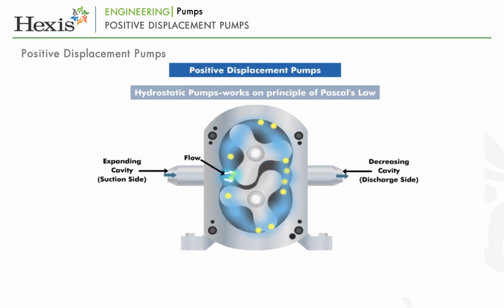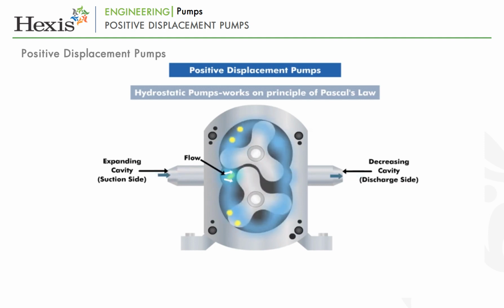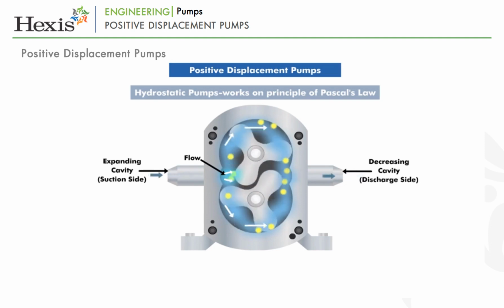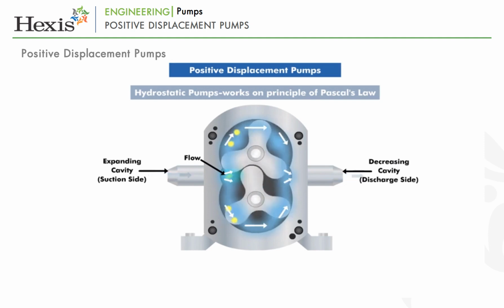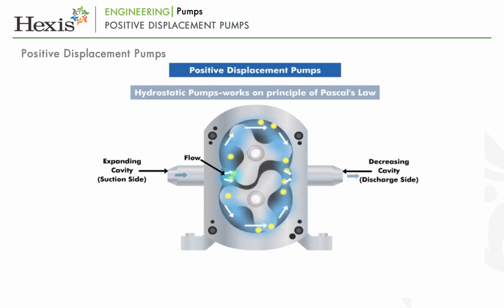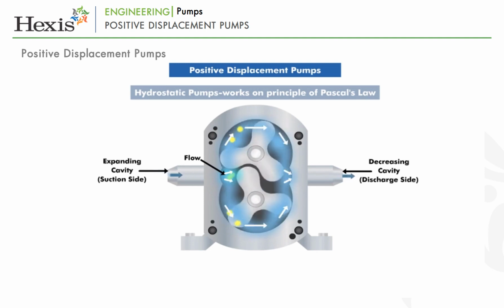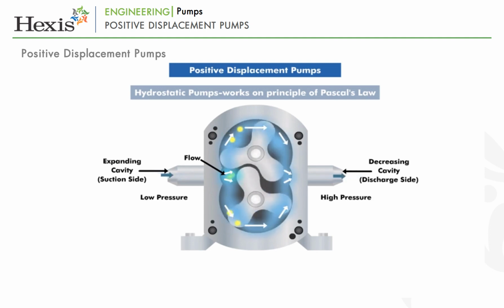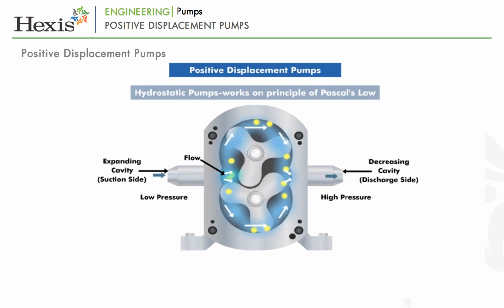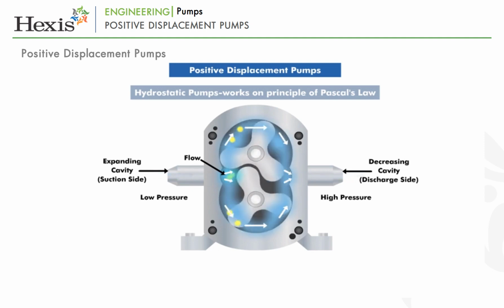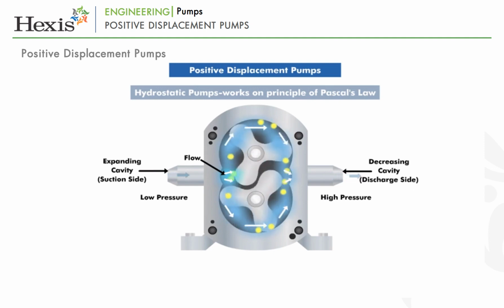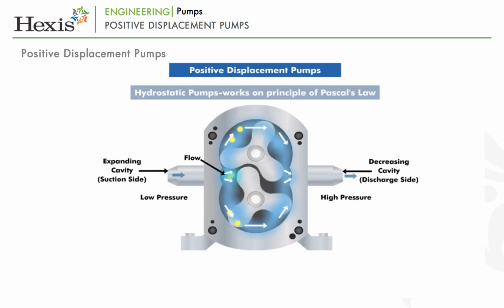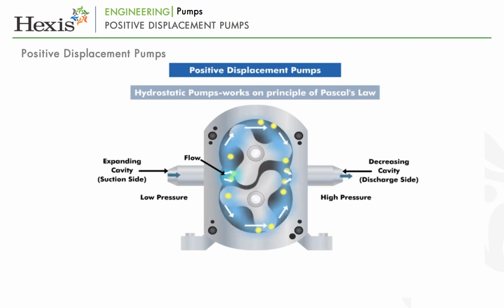The liquid flows into the pumps as the cavity on the suction side expands, and the liquid flows out of the discharge, most typically using a rotary, reciprocating, or diaphragm method to move fluid as the cavity collapses. In other words, it alternates filling a space with liquid within the pump and then moves out that liquid through another outlet, thereby displacing it.